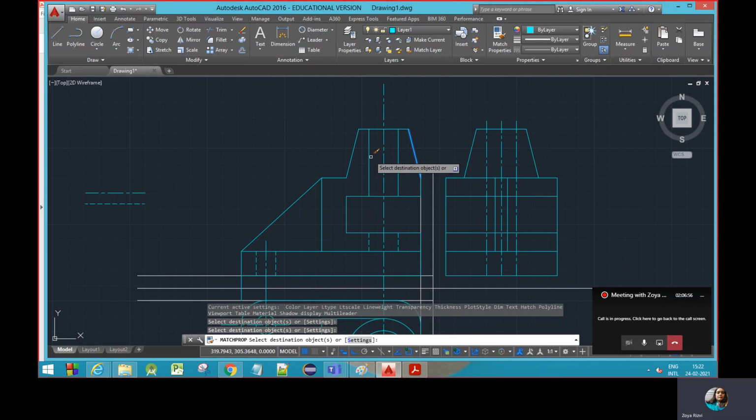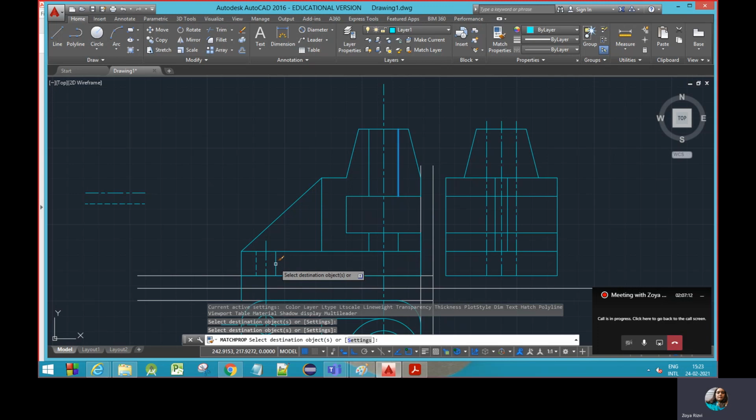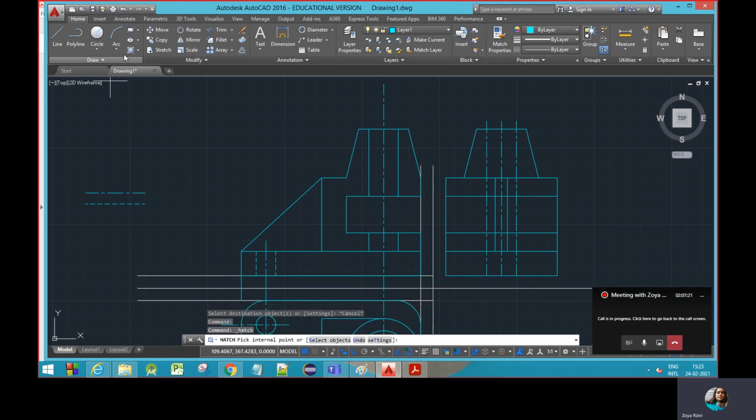If you want to remove the half part, this hidden line will turn into solid, and that one line will go away. If you have to draw the sectional, this hollow part will hold the line like this, solid line it will become, but this is not at the center, so this will not be cut. Okay, so where is the hatching going to be? Hatching will be here at this part. So I'm just drawing the hatching or sectional part for you. Just see that.